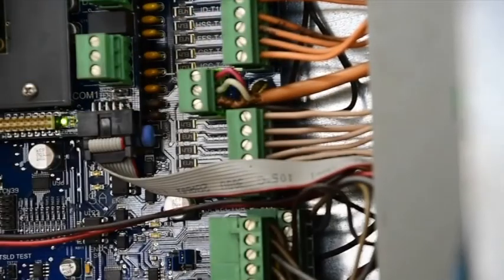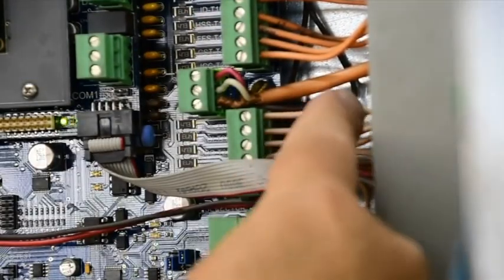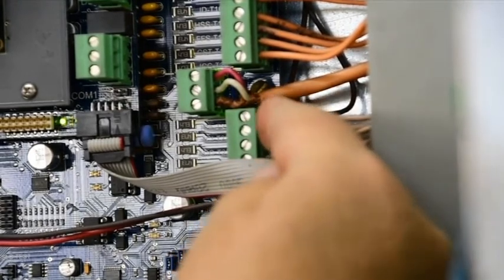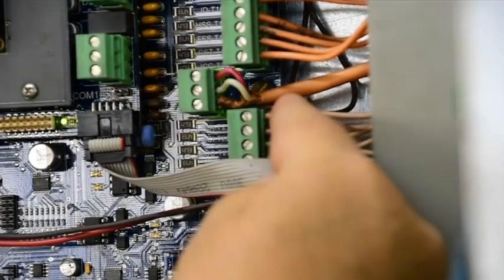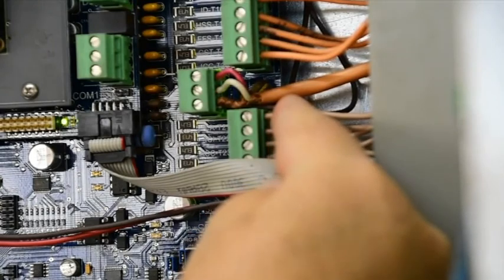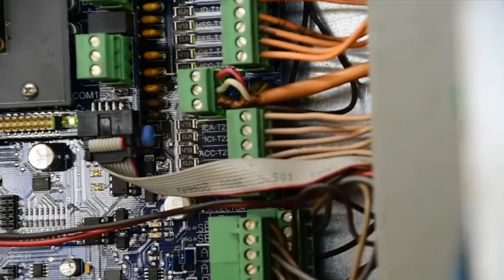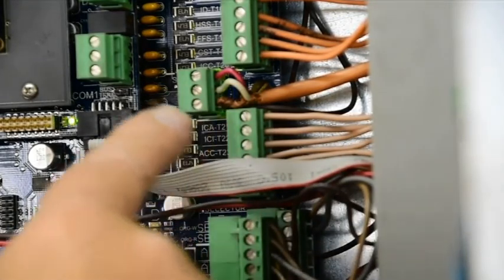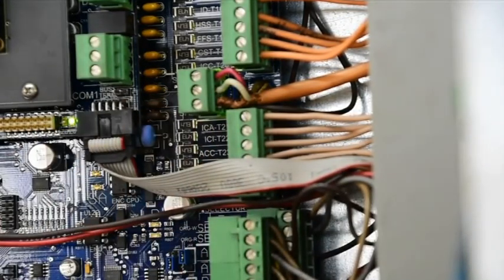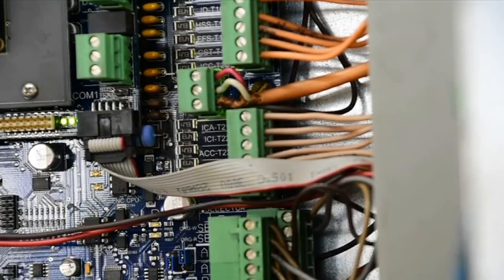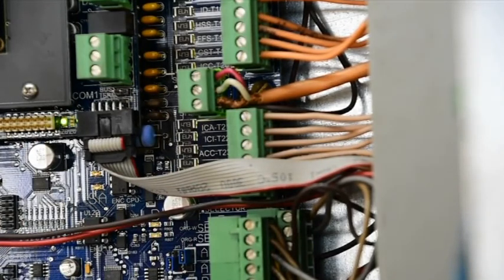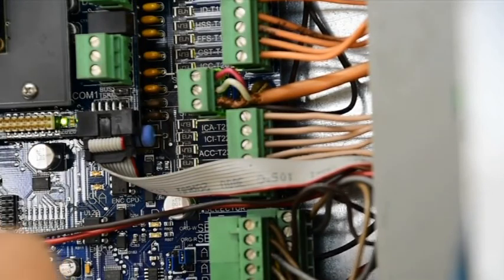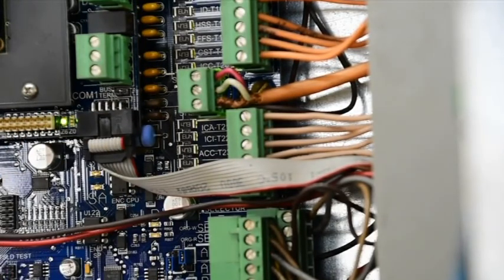Now after we put it back in, we're going to want to look closely around the terminal to make sure that all the wires went into the terminal and that there are no wires hanging out that didn't get put back in. The way to ensure that that happens is to make sure that you back the terminal all the way out. If you only loosen the terminal and then pull it out, it's a smaller opening and it tends to push wires back out. So if you unscrew that all the way before you put it in and then tighten it up, you'll be ensured that all the wires get in properly.